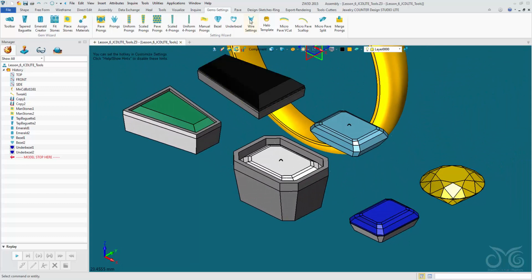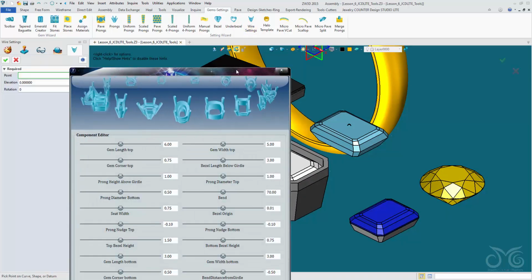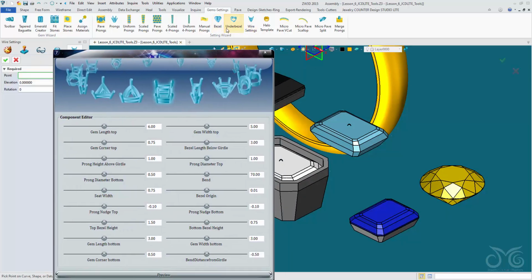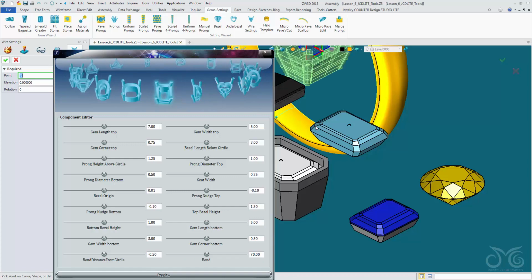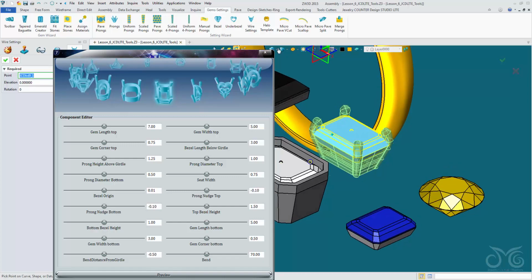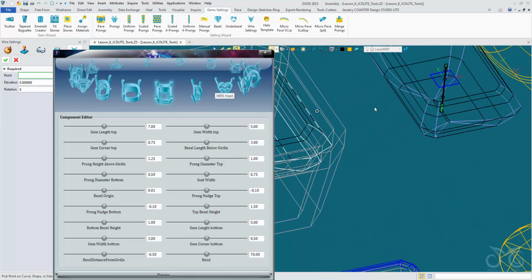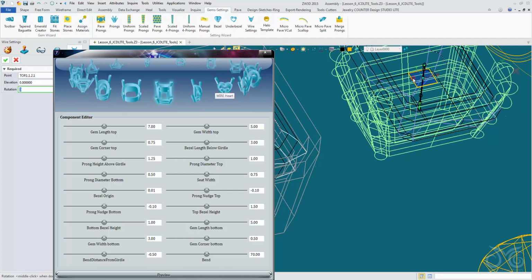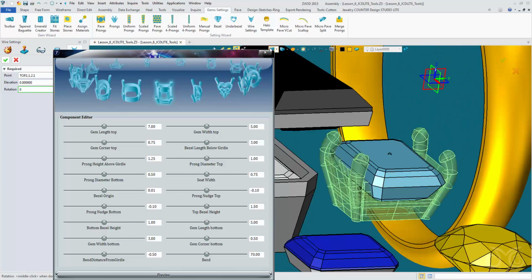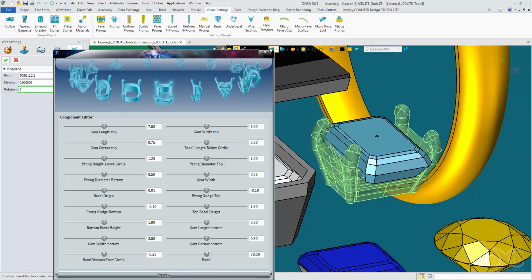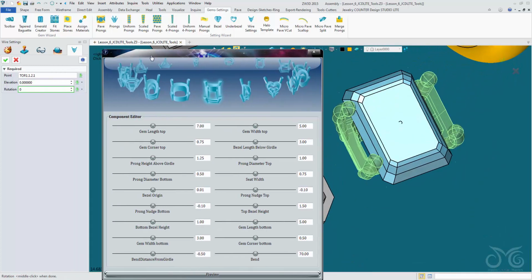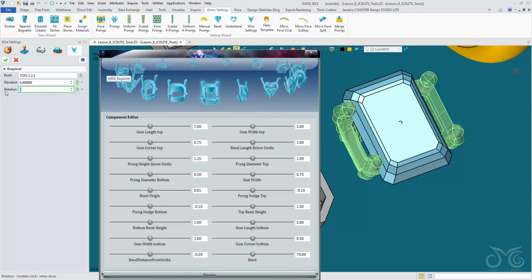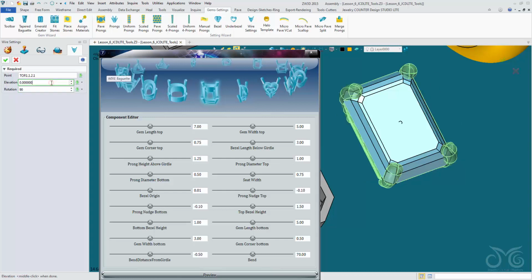Okay, so finally we have our wire setting. This works in the same way as the bezel and under bezel. We pick the appropriate wire setting for our stone, and then we place it on the same datum plane as our stone. This one we need to rotate. We use our rotation in the options panel, so we use a 90-degree rotation.